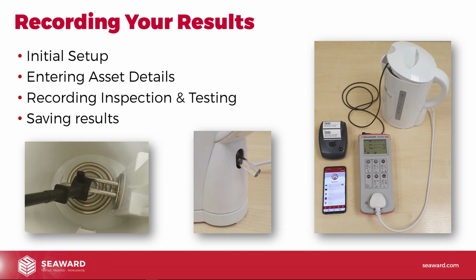So we've got the kettle, we've got the printer, we've got the app, and we've got, in this case, a PrimeTest 250 Plus device. And I've connected up the test lead to the earth metal parts inside the kettle, the element, and we've made sure that the tester is on.